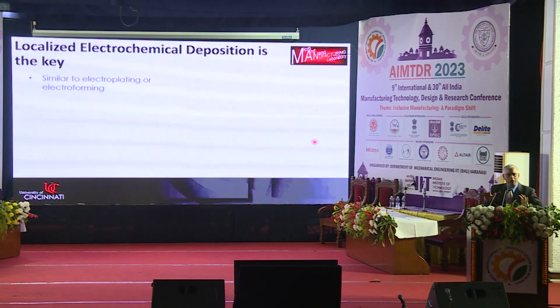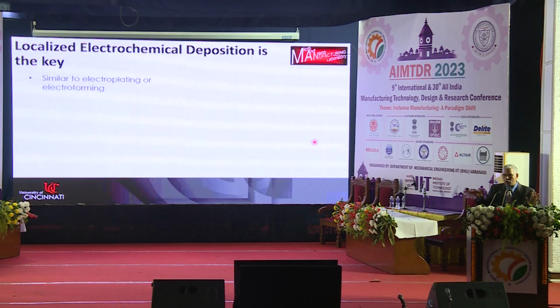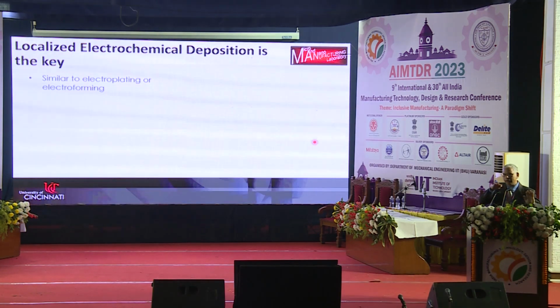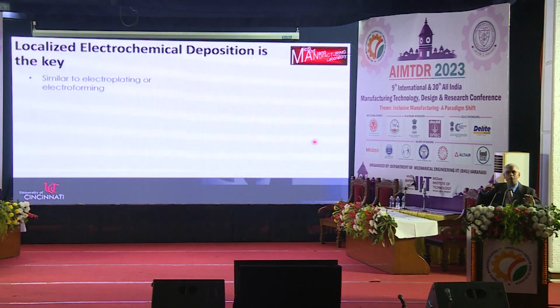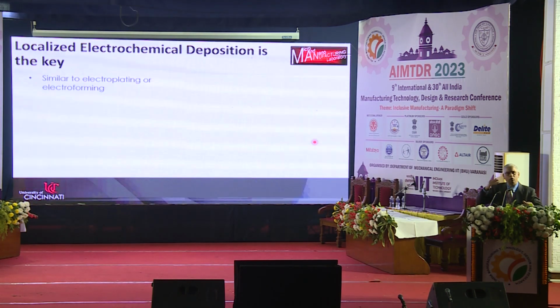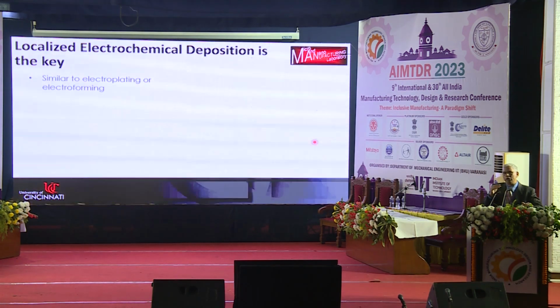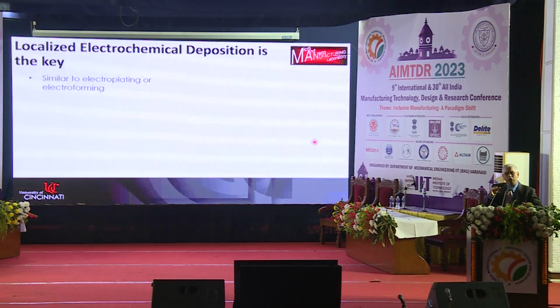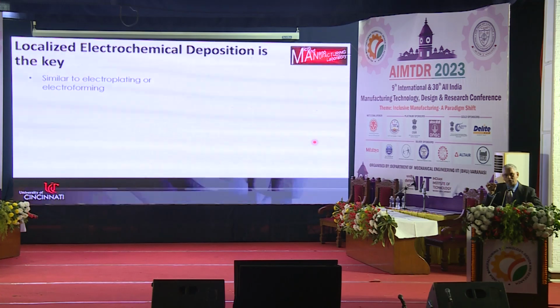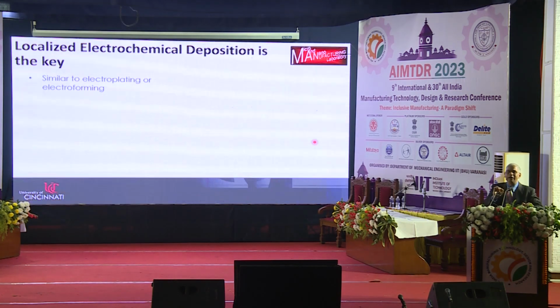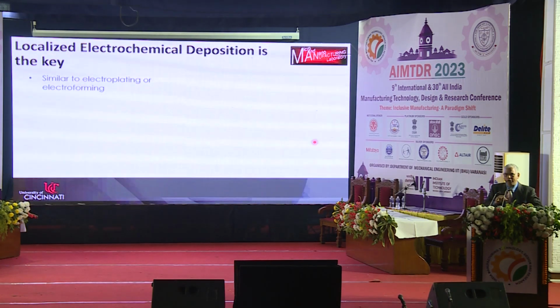The deposition by nature will try to spread out. It will try to make thin films. Then over a period of time, we can make it thicker and thicker. But if we can come up with a method to localize the deposition to one point, that is the starting point for you to achieve ECAM.